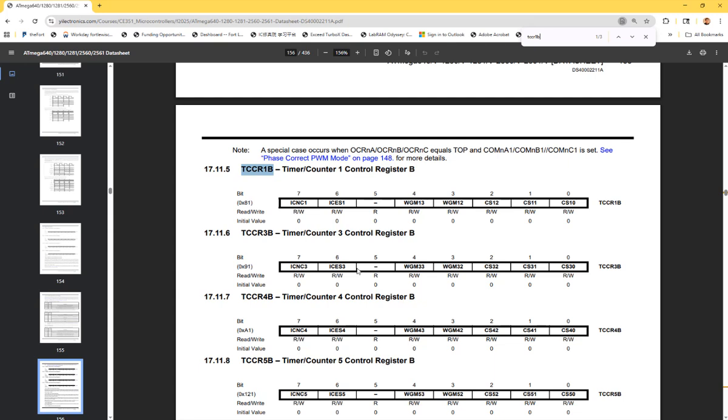This is one of the reasons we want to use registers. Otherwise, how do we change the settings? Are you expecting to use the remote? It's too time consuming. So as a programmer, we can modify them. There are hundreds of settings of registers you can modify, and you toggle one or several bits in these registers, and you can change the operating mode of the microcontroller to a totally different one.